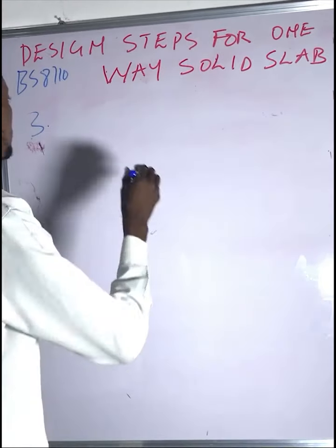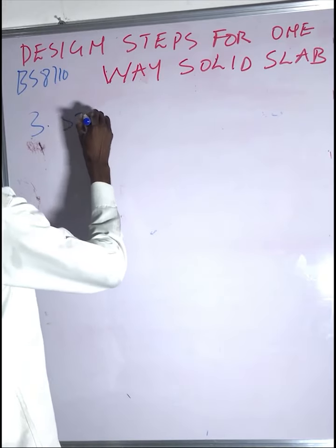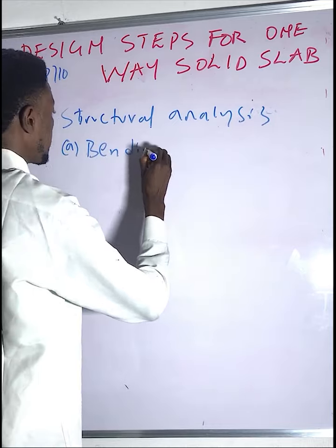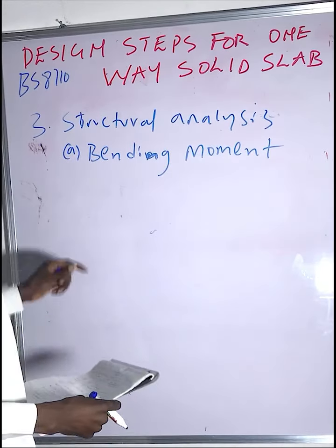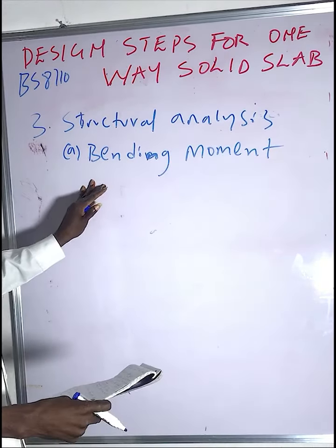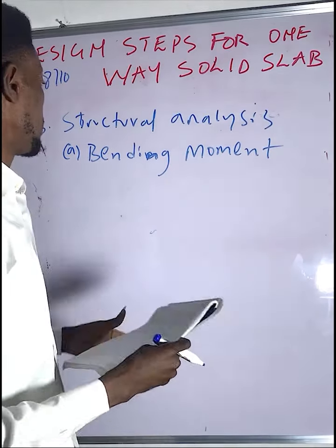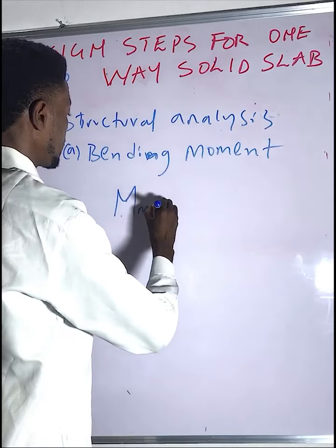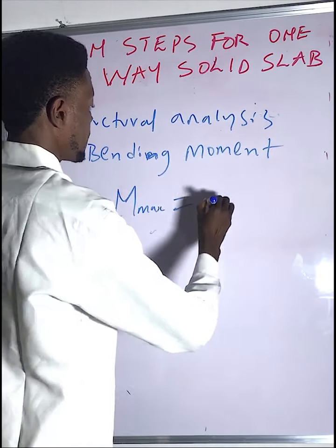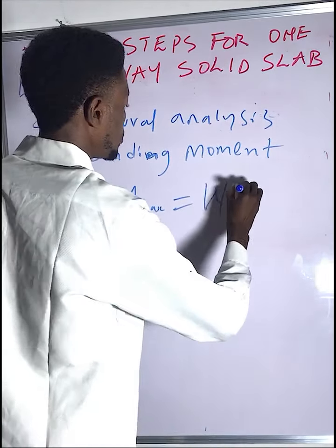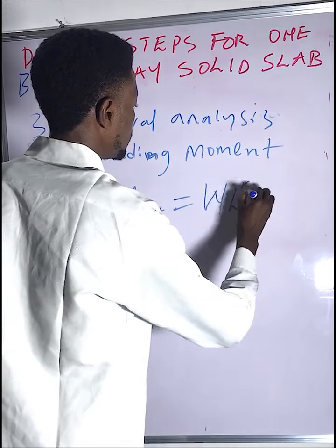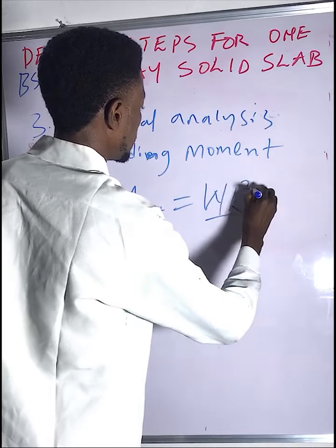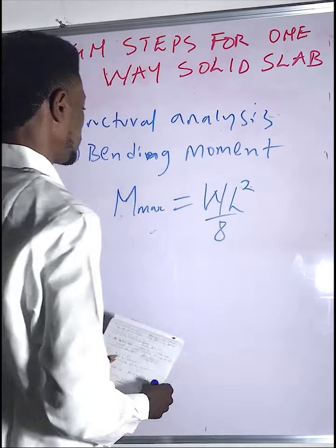The next step is the structural analysis. Your bending moment. For a simply supported beam, your maximum bending moment, M, is load times L square over 8.